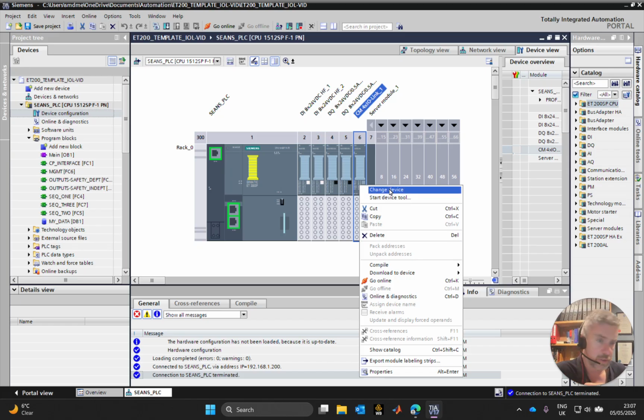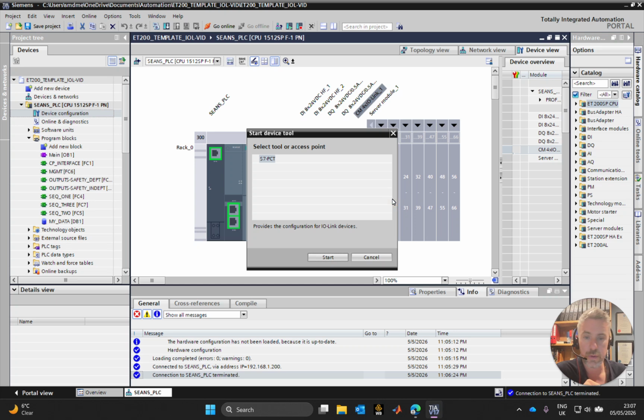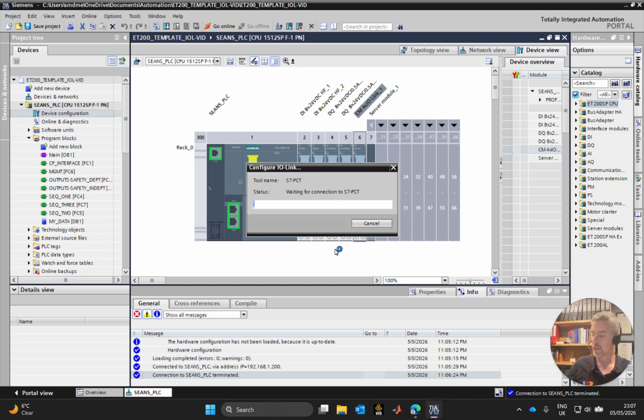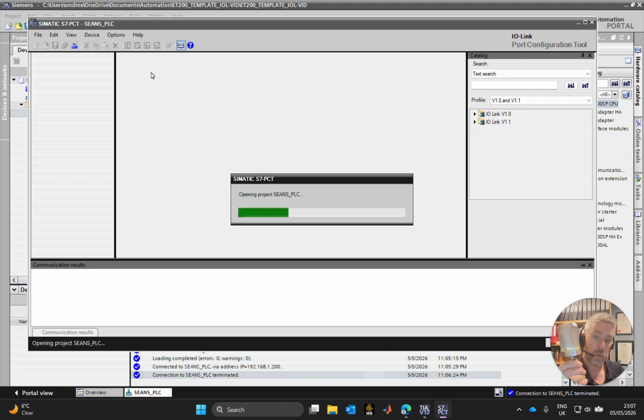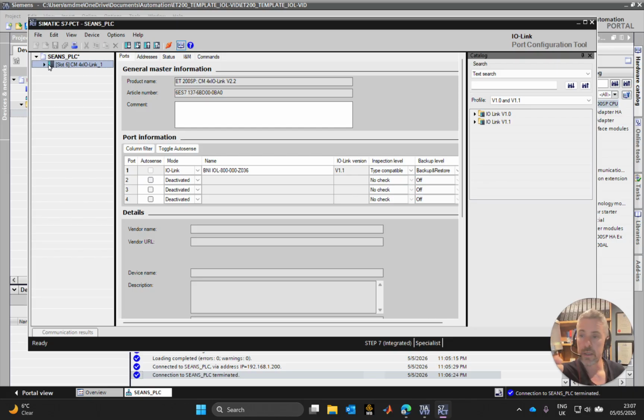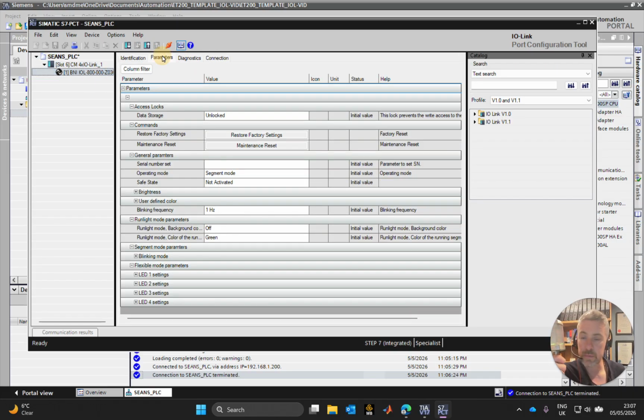I know we're at 53 minutes, this is getting a wee bit long, but I'm just going to try this. So we've seen that flash rate. At the risk of knocking myself out with high intensity, high frequency flash and light, I'll increase the flash rate here locally to 5 Hertz. So slot 1, I'll go into parameters, 1 hertz. Let's change this down to 5 hertz of a flash rate. Okay, so I'm going to download this back into the devices.